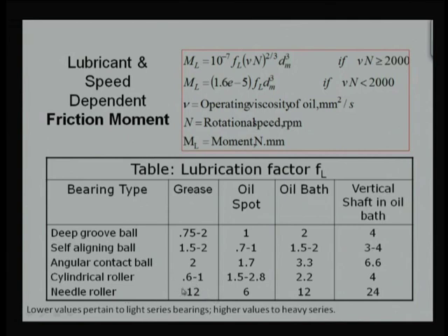So for a cylindrical roller bearing, this FL factor is 0.6 for the light series, and 1 for the heavy series or higher series. However, for the needle roller bearing FL is 12. That means it is going to cause 12 times higher friction compared to the cylindrical roller bearing when there is grease lubrication. Coming to the oil case, the difference is not that significant. Here the needle roller bearings are more comfortable with the oil lubrication mechanism. These are 6 times.